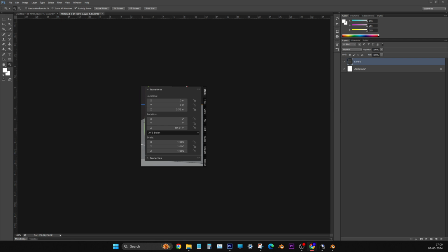In relative offset, what we did mathematically, we tried to bring this same kind of gaps. What we did in the z-axis, 1.2 or something, you put in relative offset. Do you remember that? Just select the cube. Select the cube. Go to that spanner icon, the modifiers icon in the properties panel.